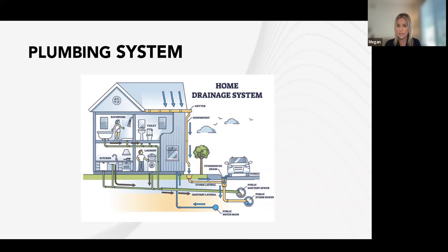Within the walls, you might see ABS now. We are moving to plastic. ABS is plastic. Older units and buildings have cast iron, and it also depends on how tall the building is. For condos, in those waste stacks, you might see cast iron if anything's above 3 or 4 levels. That's the drain side.